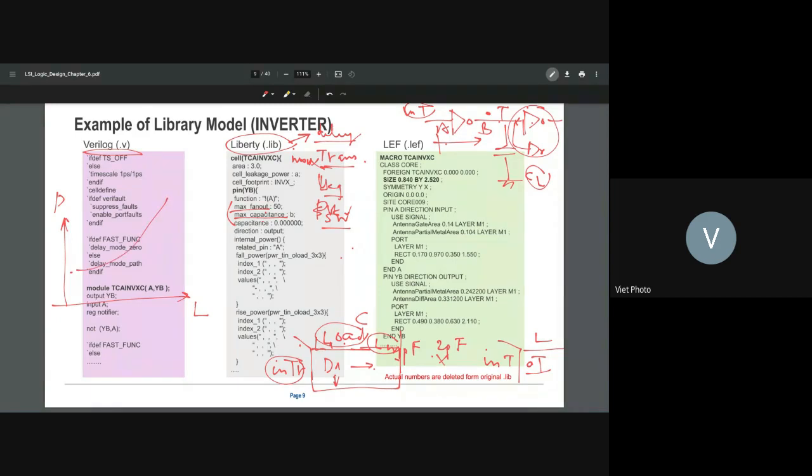With input transition, it will be like this, right? Usually it goes like this. This one is the range, the maximum, 1 picofarad here. Now 2 picofarad is outside. Let's say it's 1 picofarad, and if the load is 1.2, it's right here. Then it will extrapolate, just linearize. They take the 2 points like this and linearize, just extend that.